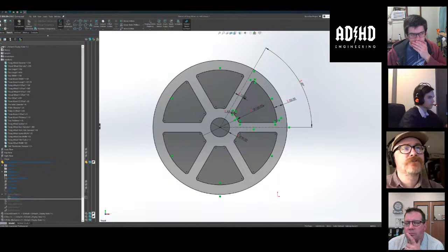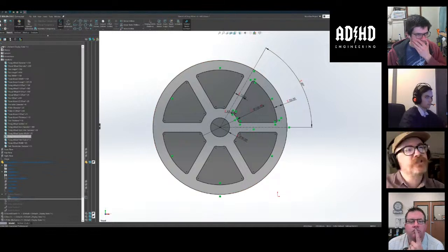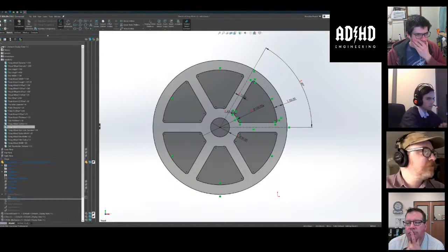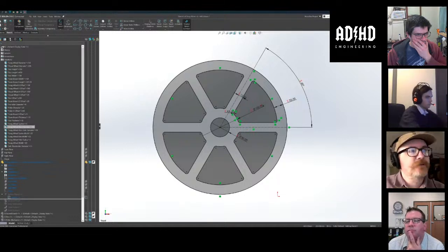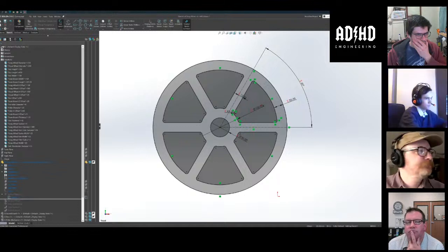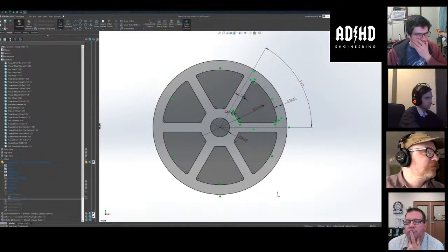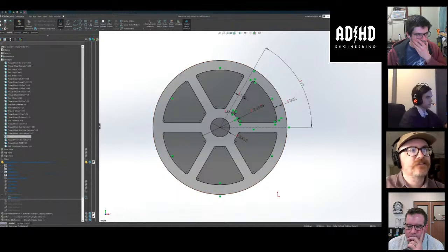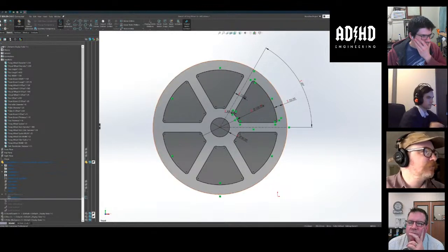So the first thing to figure out really is what your parameters are, and in this case, they're going to be right here. I chose 6 spokes, but we can change that to 5. That's easy. Wheel hub diameter, I decided to make it 100. That's this circle, and it can change to whatever. Wheel hub hole diameter, I decided that's 50. Wheel rim width, that's this here. I decided 25, can make it whatever.